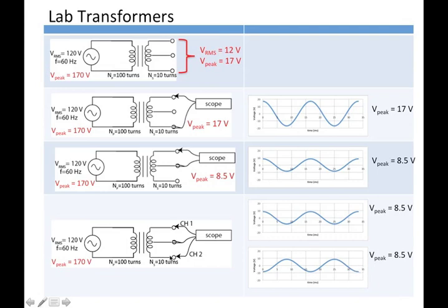Okay, because in the end, no matter what we call 0, the difference between the outer taps has to be whatever the signal is. In this case, it's 17 volts at the maximum point. So we need 17 volts or whatever we read right here across each of those leads. And so what we measure, though, is relative to ground. So we're getting half of it here and the other half here. So they end up being out of phase.